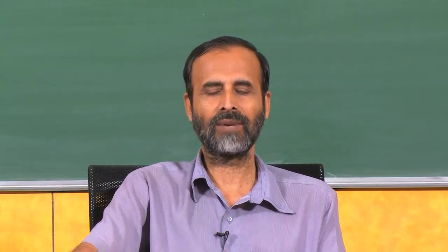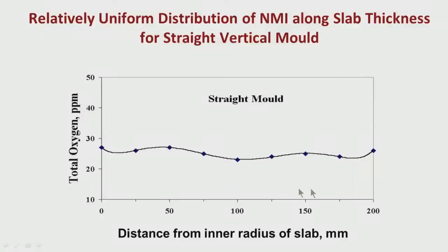So, whatever defects were inside the cast slab, as you are rolling it, this 200 millimeter thickness will become, when you are hot rolling it, maybe 5 or 6 or maybe 4 millimeter. Whatever defects are distributed in the whole bulk of the cast slab will try to come to the surface because the surface area is increasing. So, the more you roll, the more defects get exposed to the surface.